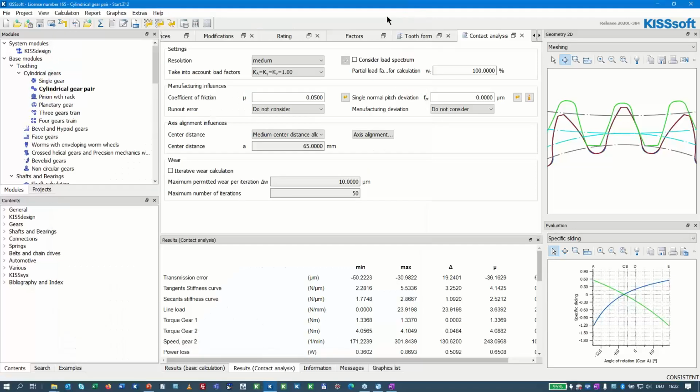Now back to the question of the no backlash condition. Zero backlash under all operating conditions is practically only possible with a pre-tension system. It means a variable center distance where you apply, for example, a spring force, which is the most economical solution. Or that you have a non-constant tooth thickness on one gear and you push it sideways. That's also a design solution.